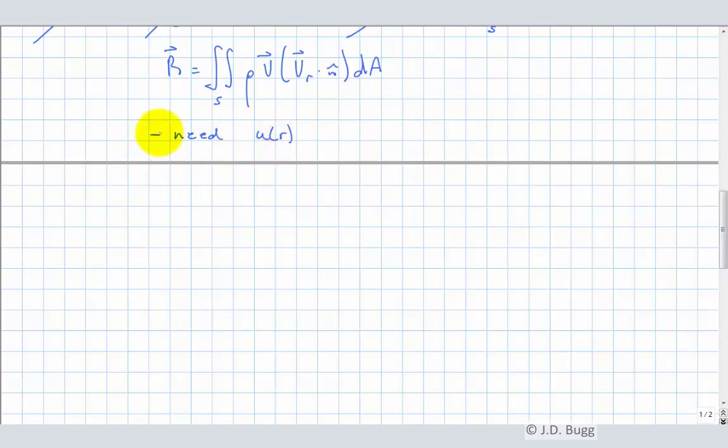Okay, and it's a u component of velocity that we're looking at here because it's the velocity in the x direction. We've been told that this function is linear. So the way I'm going to write this down to get started, u will be uc, the center line velocity, times 1 minus r divided by R. So what is this?